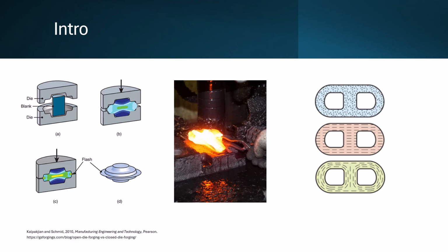This process of material deformation presents an advantage over some other material processes, as it has a beneficial effect on the microstructure. During the deformation, the grain boundaries of the crystalline structure are forced along with the material, resulting in aligned, smaller grain boundaries and increased part toughness and strength.